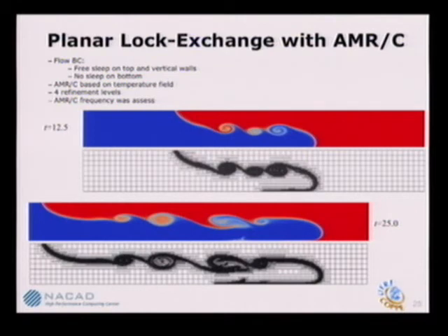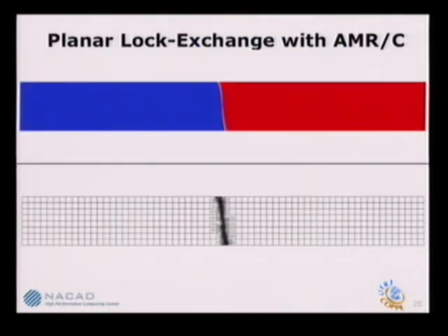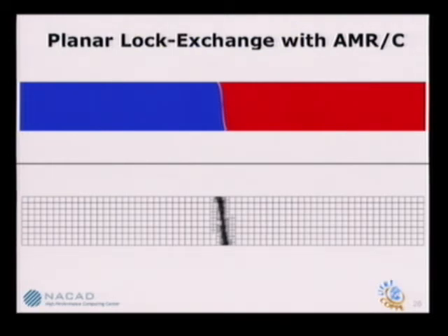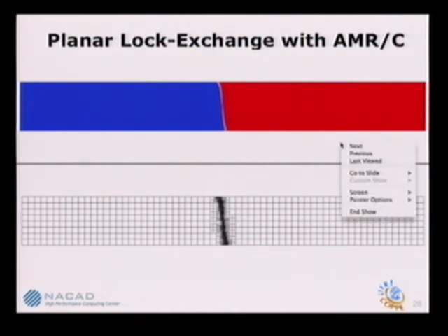It's not clear at the moment that this will be enough. Probably due to these boundary layers around here, perhaps we have to look at an error indicator based on the Navier-Stokes equations. But so far, all the computations done before in 2D use only temperature. So it's something that we are investigating because there are some strong boundary layers occurring here. And maybe I'm going to need to look at a Navier-Stokes equations error indicator. And there's a movie here. Again, we're looking at the projection, but this is a slice of a 3D computation.